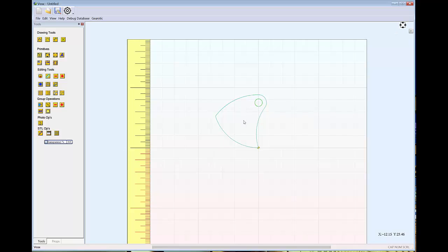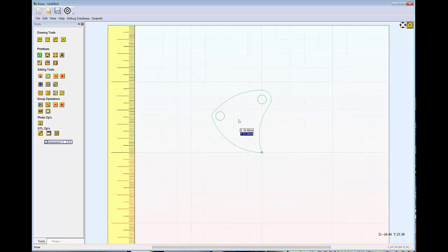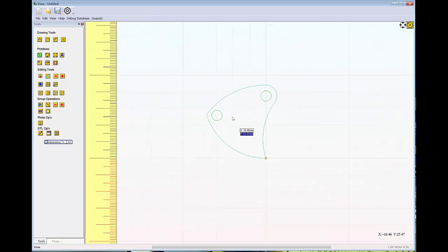Now we need something to pull that vane out from the center, so I'm going to add another circle right here. It's not real important where you put it, but you should keep it about equal with the radius of this second circle so it stays out of your way. But again, it's arbitrary, so you can just pick a point, enter a circle, and I'm going to make that a 6.25 millimeter circle because I'll just shove a wooden dowel in there. Okay, so there's our vane.